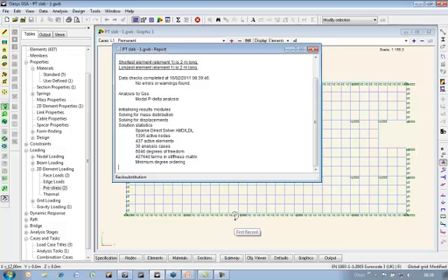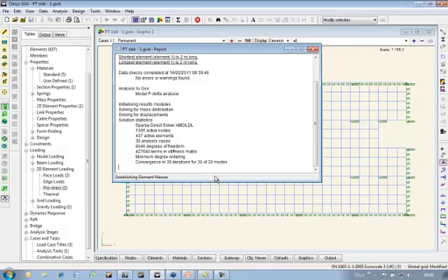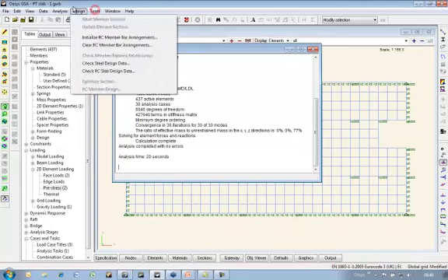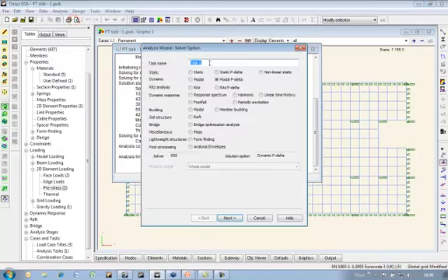The end result of this will be to reduce the frequencies of the slab, and possibly then induce more frequencies. And of course, PT slabs tend to have more of a footfall problem because they are much lighter than flat slabs.